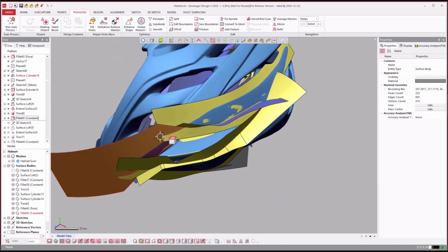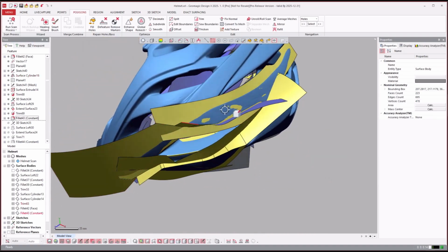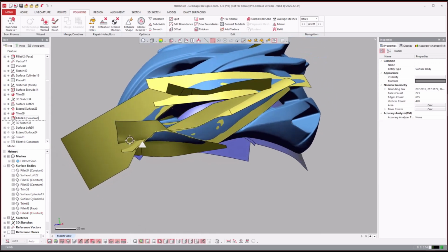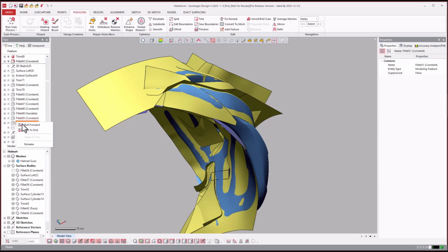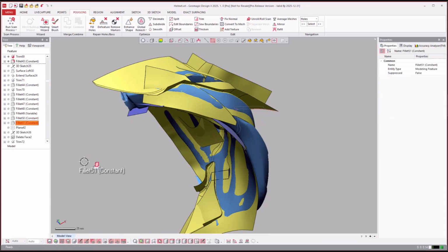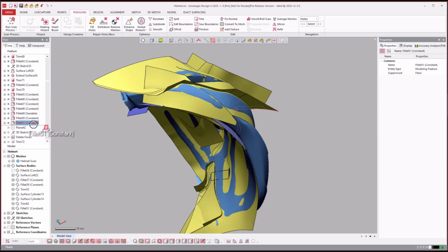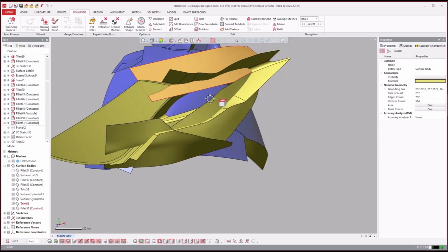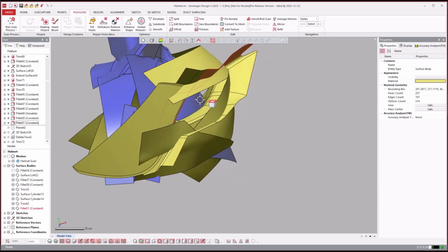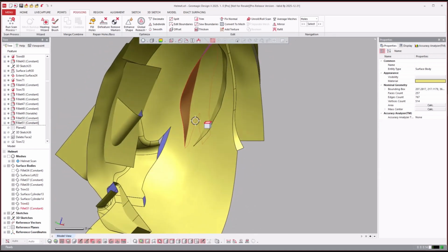You see, now we're working our way around here. So we did these there, and now we are stepping forward. And all these fillets are a sign that stuff was trimmed together, and they're adding the fillets to it. So it's usually a good break point in a history tree. Once I see a bunch of fillets going on, it means they completed a section and they're dressing it up with the fillets. Yeah, so you'll see here that they basically designed that whole pocket that connects.